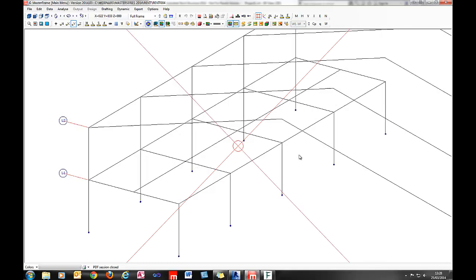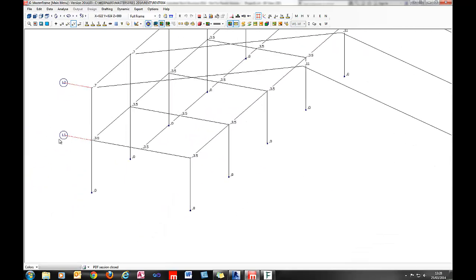However, the level in MasterSeries didn't have any actual linkage to the level in Revit. If I change this level in MasterSeries, what actually would happen would be you would get a new level in Revit created at that. But now we're actually mapping, doing a proper linkage between the levels and storing a proper representation of the objects between MasterSeries and Revit.